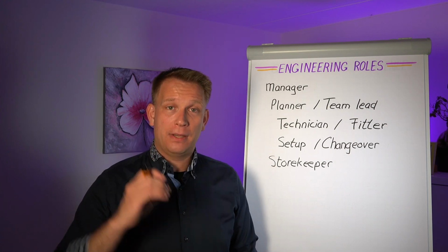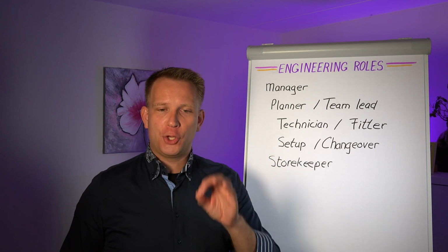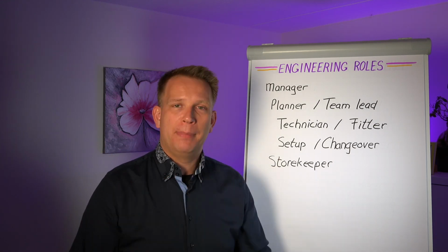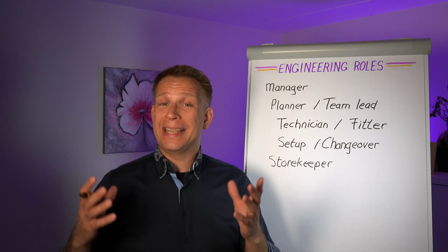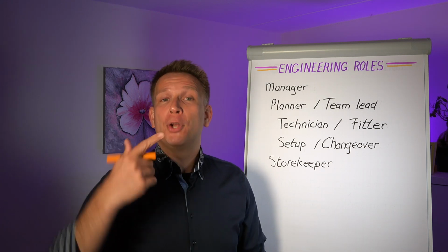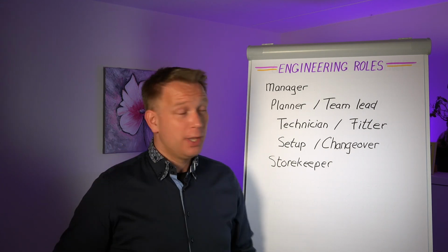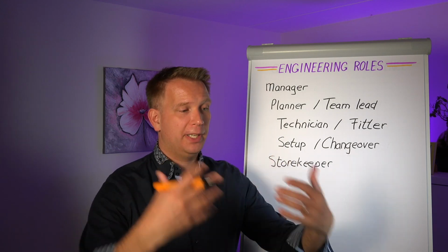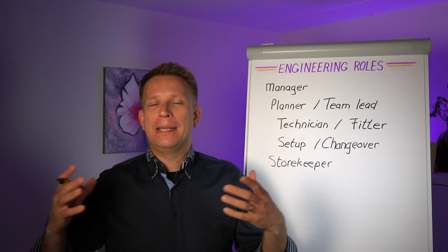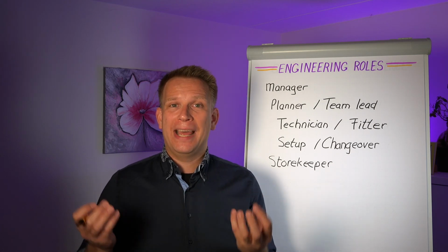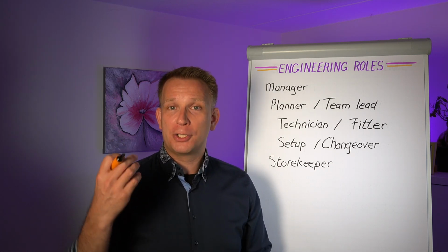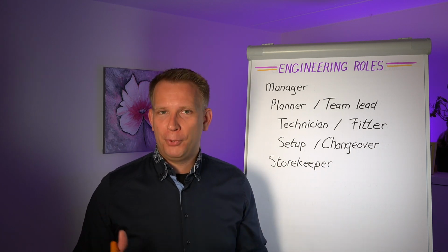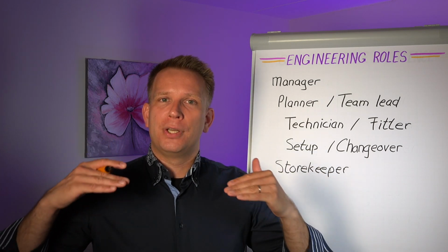The basic thing for a storekeeper is to make sure that there is good inventory management on spare parts. Now, if we are talking about the preventive maintenance pillar, if we're talking about maintenance management, this is a key part of controlling cost, but also of making sure that your maintenance team can do their job. So it's an important 5S type of job. Where 5S for production makes sure that all the materials and all the tools are there, the storekeeper in the maintenance system makes sure that you have all of the spare parts that you need. Maybe also the more specialized instruments and tools are under their purview, and they manage the stock levels.